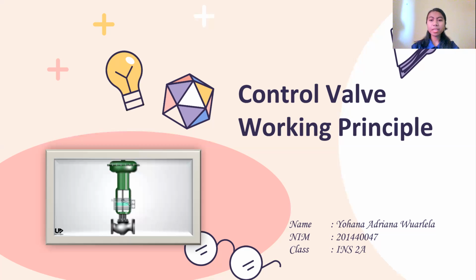The driving component is usually called the actuator. The actuator movement can be linear or rotating. Using it allows you to easily control the process of opening and closing the fluid automatically. Thus, you do not have to worry about closing or opening the valve manually while the valve is operating. I will talk more about the working principle of the control valve based on its type, control valve components, and function.